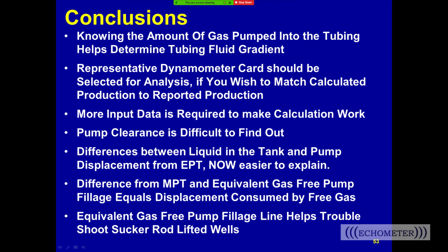If you have a really big plunger and it's a shallow well, the big plunger causes the discharge pressure in the plunger to increase during the upstroke because of restricted flow out of the pump into the tubing. That can cause a bottled up pump increase in load, and then it will echo up and down the tubing and make a wavy pump card. So that peak load is impacted by bottled up pumps in shallow wells, and you'll see a wavy line, and that's a pressure force caused by a large diameter pump and a shallow well.